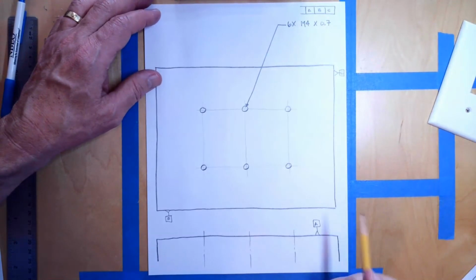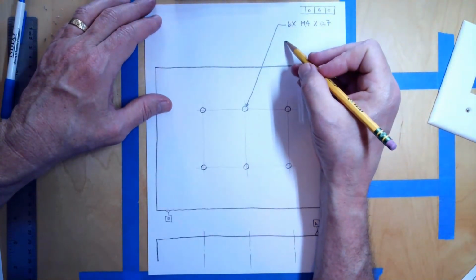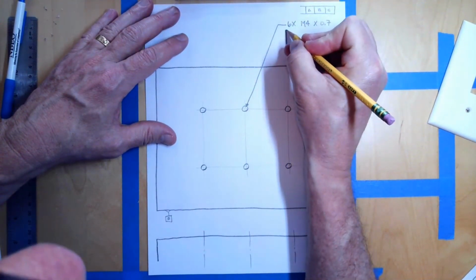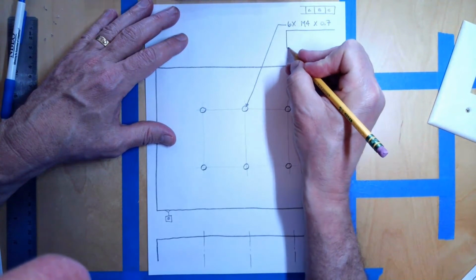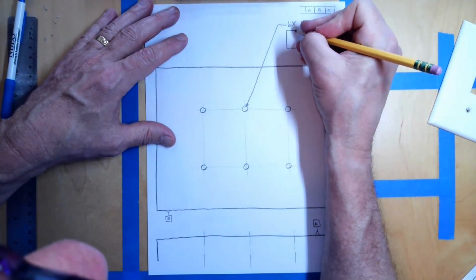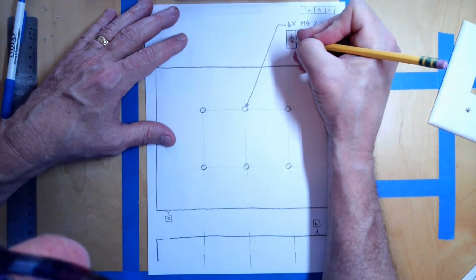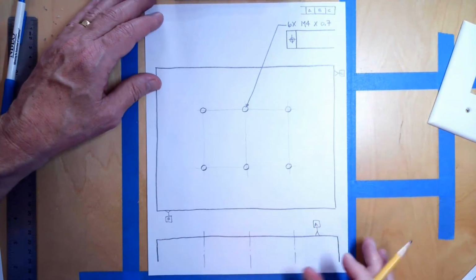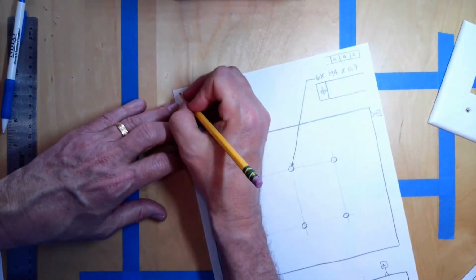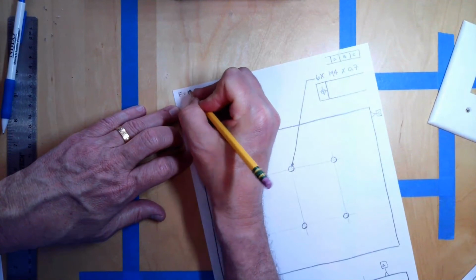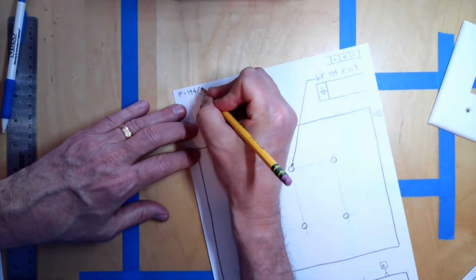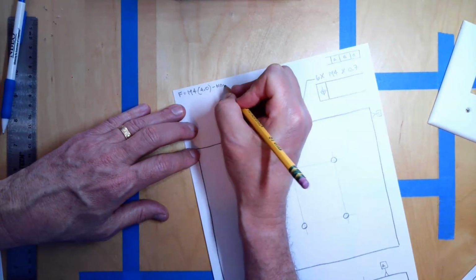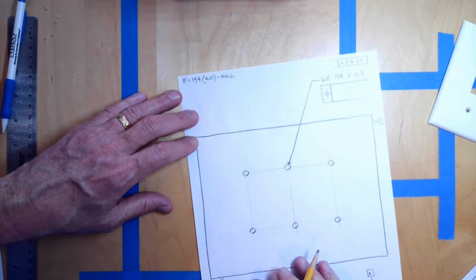All right, now let's figure out the tolerance here. We're going to use a composite positional tolerance. How are we going to start with this? Well, this is a perfect example of a fixed fastener case. What are the things that we know? We know that the fastener is an M4, so that means it's 4 millimeters in diameter, and that is its MMC size.